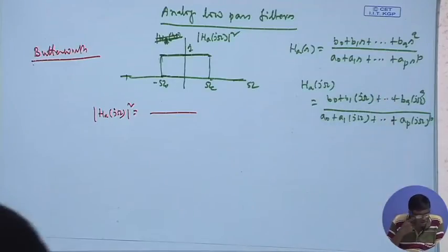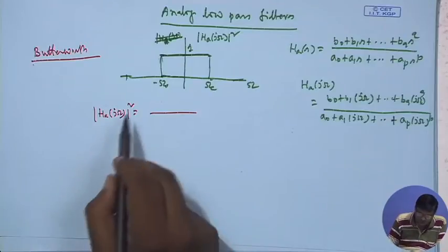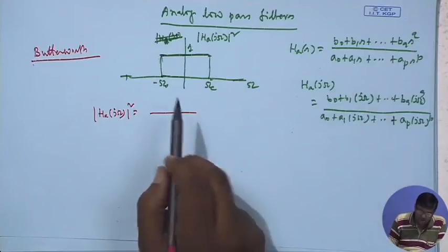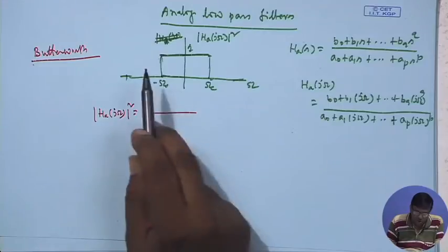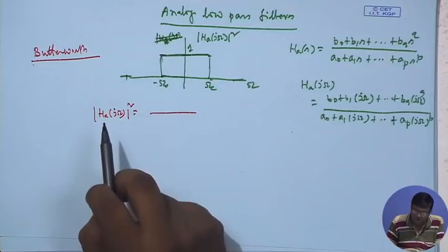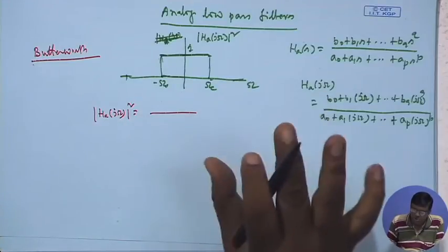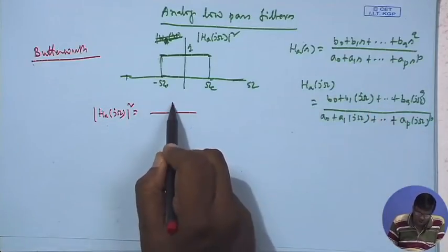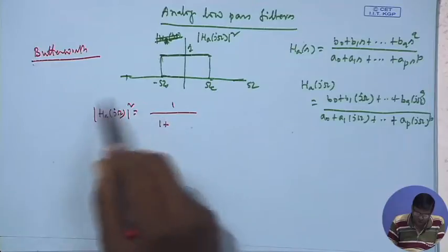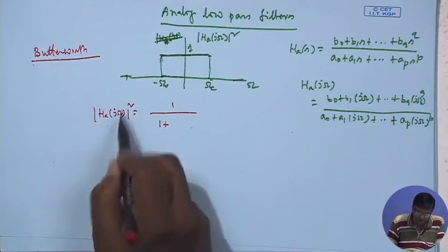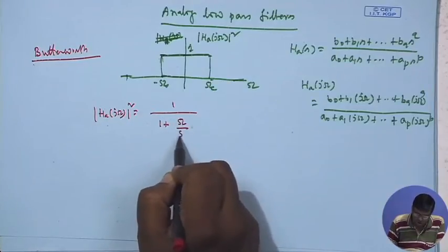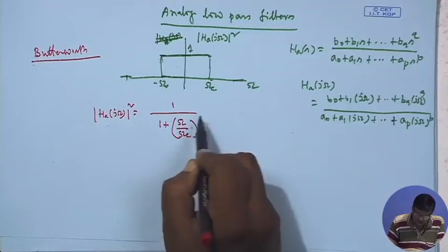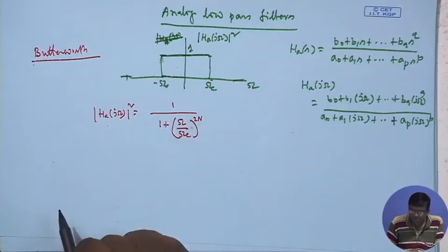But the function that we are using is called the Butterworth function. For this, H(j omega) will be a particular type, so that when you take the mod square, it will be 1 plus, and mod square means it will be real, because you are taking mod. So, obviously, it will be omega by omega c, suppose, whole to the power 2n, where n is an integer.